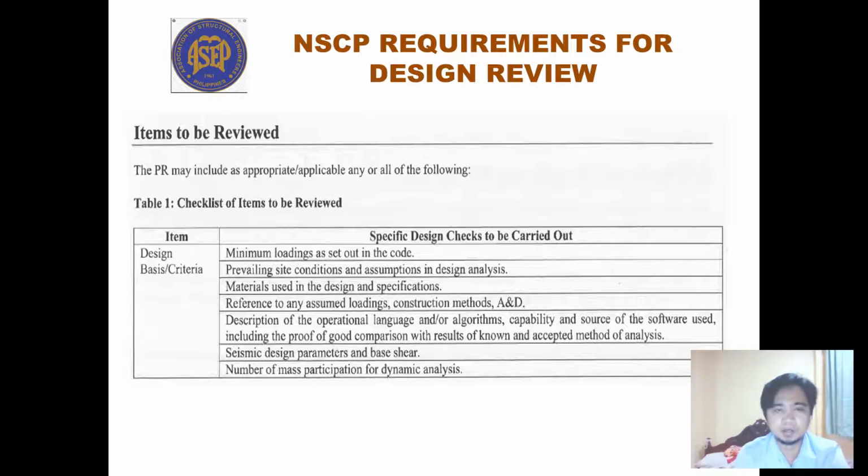You should consider the factor. What is the magnitude? What are the magnitudes to be considered in your design? And then your factors related to base shear. Okay, so all of those are clearly defined in the Structural Code of the Philippines, and we wanted to assure that those are included in your design basis as well as the criteria.